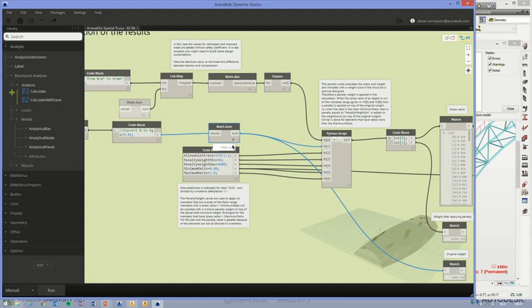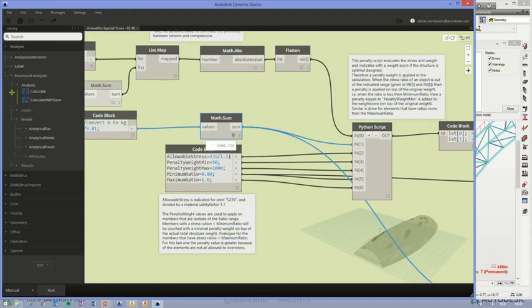You hear me coming already? I want to find a structure which is as light as possible, where all the objects have stresses within the allowable stress domain. So therefore, I need to have the reaction forces, and I need to have those stresses. So that's a specific part that has been added to that node, so that you can get those results into a list. A list will represent the maximum stress and the offset reactions.